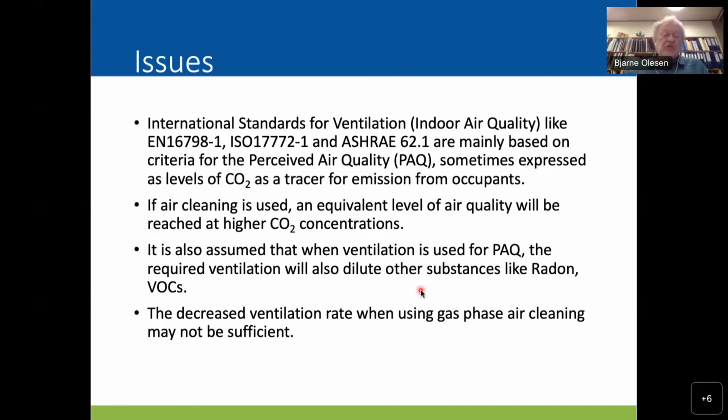What is also assumed in some of the standards is that if you ventilate for perceived air quality, the required ventilation will also dilute other substances like radon and VOCs. But of course, if you now lower the ventilation rate because of the air cleaner, which does not work on radon, you may have to check if you still have enough outdoor air for diluting radon.